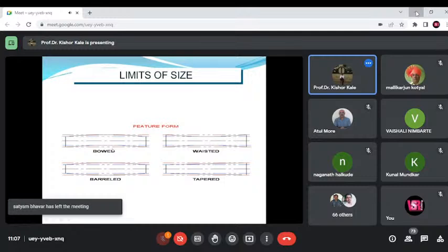Now the placement of datums. The datum may be at a hole. Anywhere on this hole, a feature of size such as a hole, can be a datum. So the hole is a feature, or the surface is a feature, and that can be called a datum. You can see 5.5005 plus or minus 0.005. That can vary with respect to this datum. So this feature can also be called a datum. We are talking about the placement of datums. A datum can be placed on the features used for GD&T.